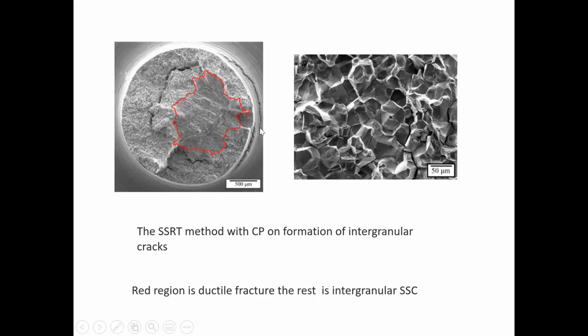These are cracks caused by hydrogen embrittlement in the sample. And if you look at the higher magnification, these are the grains, and you can see the cracks in the grains. If you look carefully here, I'm just drawing the cursor around where I can see the cracks myself. They're all over the surface. There, cracks everywhere. And that's most of the surface. The only bit that was not affected by the hydrogen was in the red region here, which is that island here. Most of it's been affected.